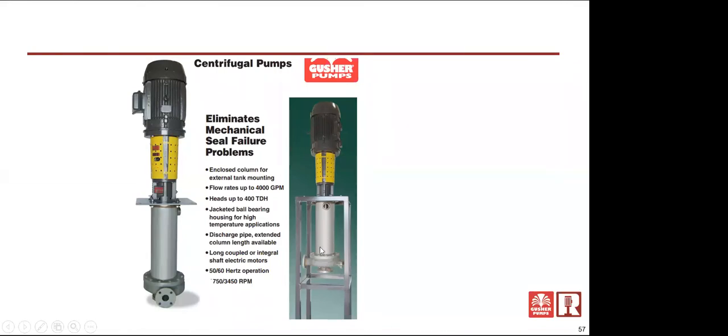And we can make this pump actually be able to run dry, meaning that if we suck so much air into it that it lost prime, it would continue to run without being shut off, without damage, until that liquid level came up to another level where it would be able to get into the pump and prime it up again and take off and pump fluid.